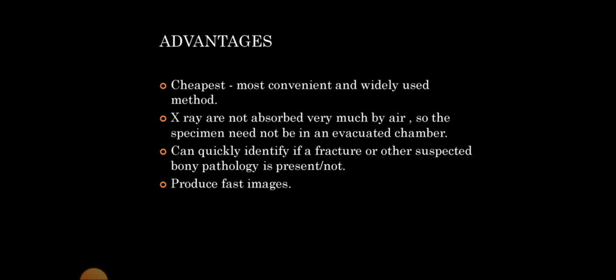Next are the advantages. When we take an x-ray, it is considered the cheapest, the most convenient and widely used method. X-rays are not absorbed very much by air, so the specimen need not be in an evacuated chamber. The method is somewhat easier. When we compare to other techniques like MRI and CT, those chambers are not needed for x-ray.